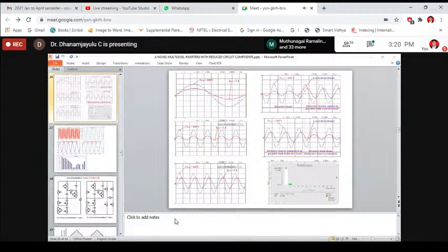By having only solar PV, we extract energy from the solar PV and give it to the load. That is one of the issues, but we need to connect to the grid. Then you need to design LC values, because obviously THD is high, so you need an effective filter design. If THD is quite high, it is very difficult to design your LC values and it will increase the size also. So getting LC values is very difficult in real-time implementation.